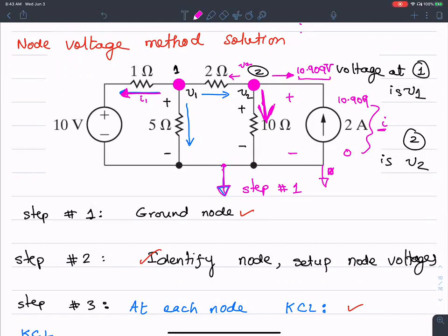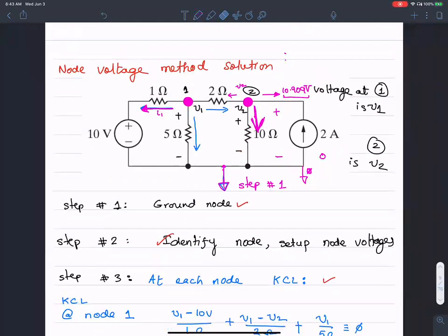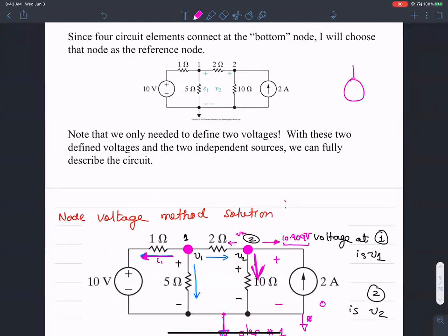Okay, thank you. That makes more sense. I was just treating it like a regular current, but I guess it's different because it's a current source, right? The only thing about a current source is that the current through it is set, 2 amperes. The voltage between its terminals does not matter. That can be set by the rest of the circuit. Even if this is 10 volts or even if this is 3 volts, that does not matter. The current is constant. But for sure, there is some voltage around that current source. Okay, thank you. Other questions, please.